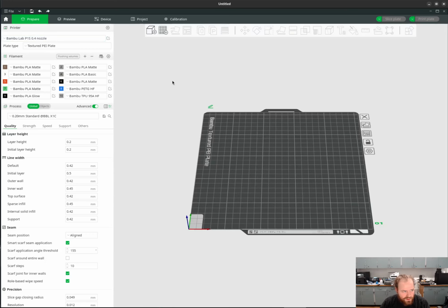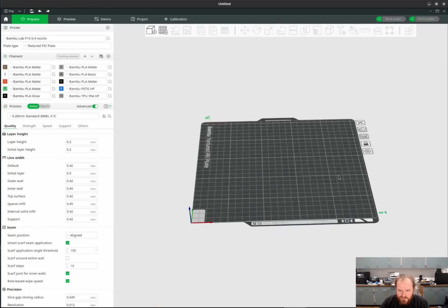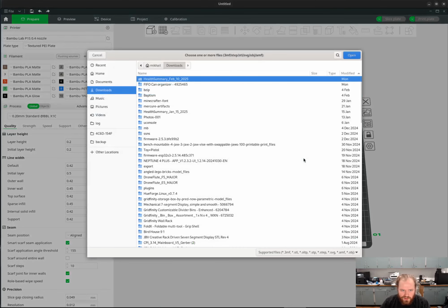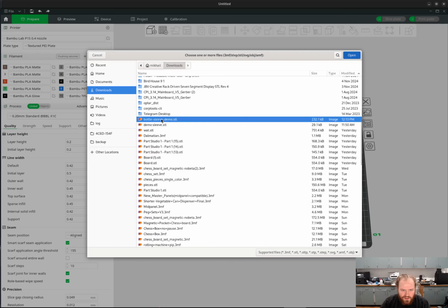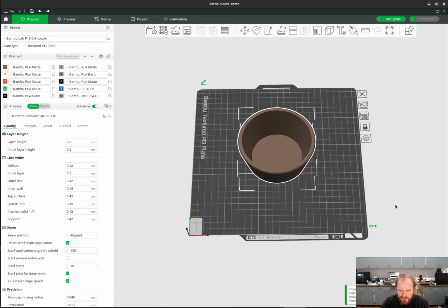this is Bambu Studio. I believe it's a fork of a different one, but they all do the same thing. What you see here when you just open it represents the print bed that the printer will print things on. Then I will import the STL file we just downloaded. There was a dialog asking if it's millimeters or inches.